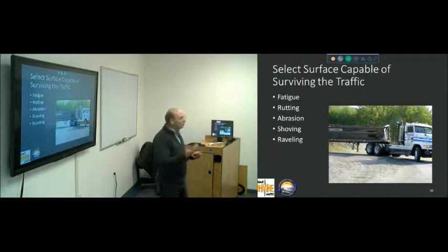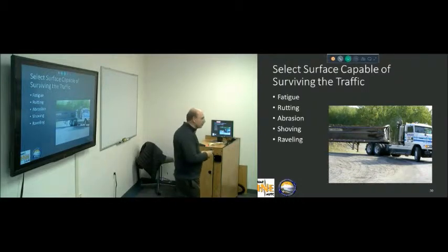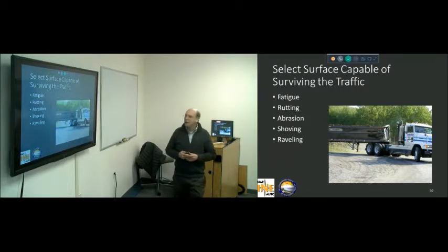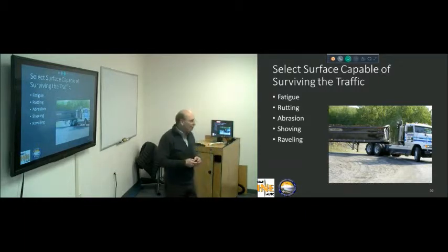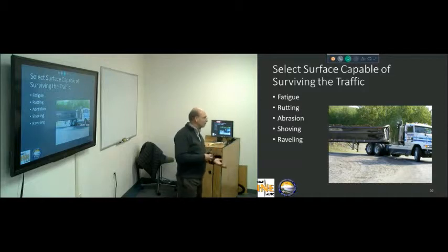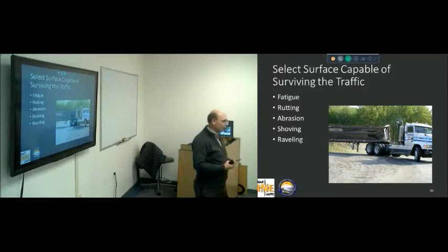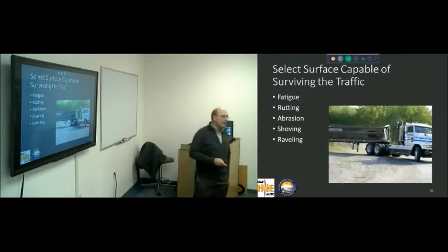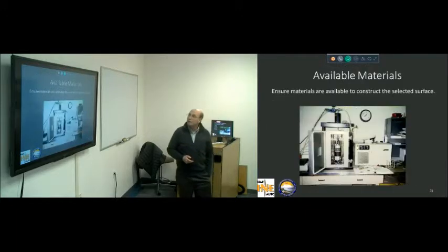And then raveling. Raveling usually occurs because you don't have enough asphalt in it, and so this whole thing is a balancing act with the materials that we're talking about in order to get what we want out of it. That's where your materials and mix designs become critical. Don't just assume that this is all going to occur on its own. It has to be planned, it has to be in the specification, it has to be in our procedures in order to make that work.